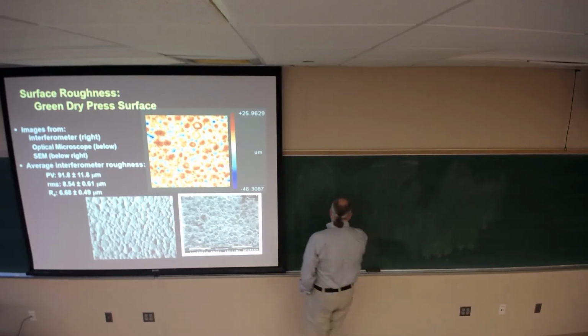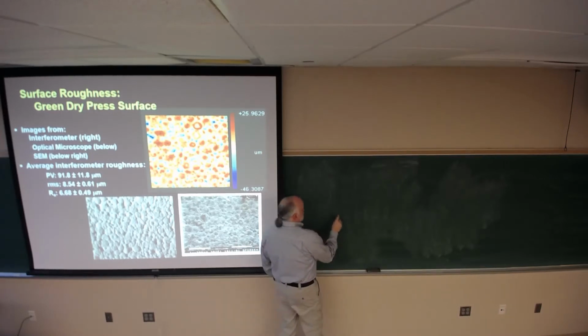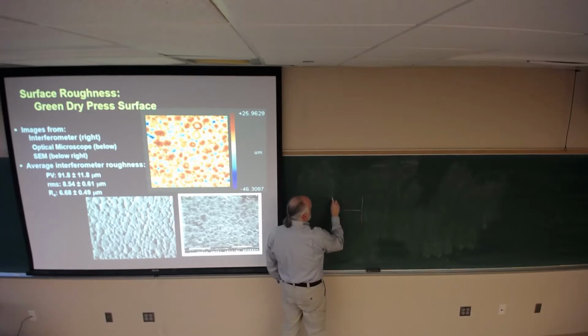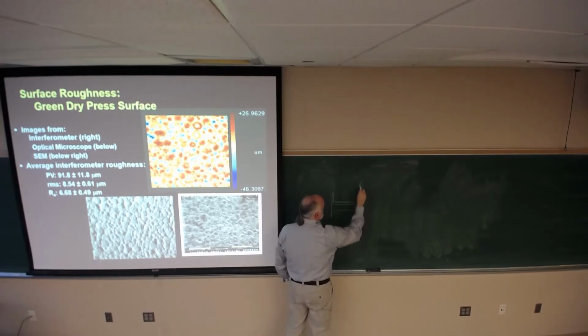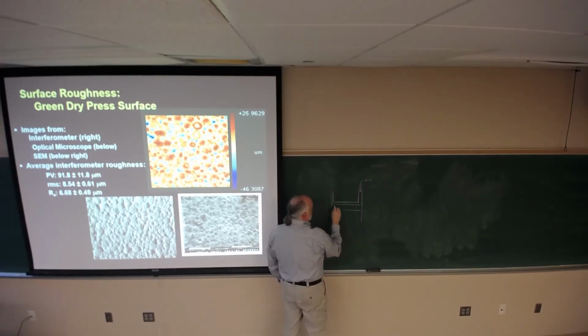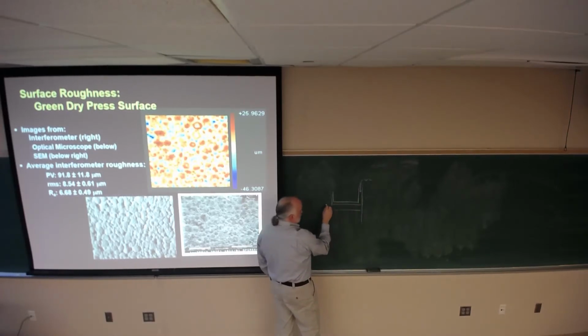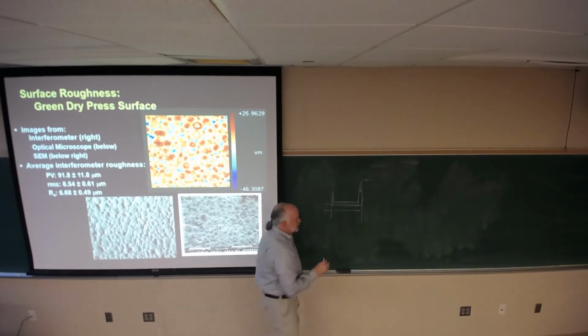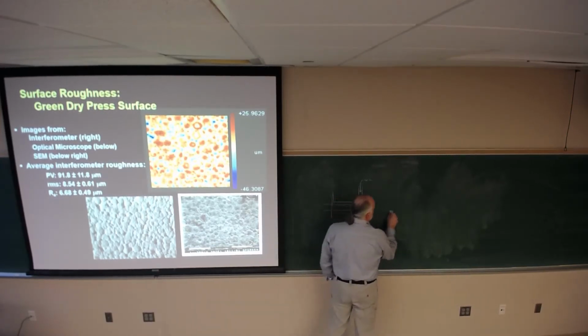So what you have is, let's just do it really simple. I'm not going to draw the cross-section of the plate. You have a steel platen, okay? You have your die wall, okay? And then you have a die that essentially comes down, looks like this. Behind here is a steel plate, and then this is filled with oil. And so your granulate is here, and when this presses, they bring the press down, then they lock the punch, and then they pressurize with oil, and then this membrane will deform based on the fill variation. So what you get out is a piece, I'm going to exaggerate, it looks like this, right?